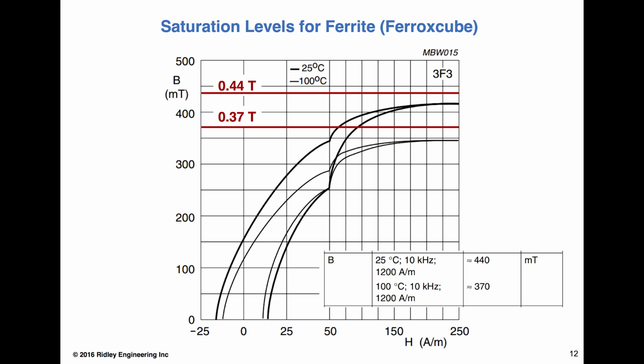We have to define what planar means carefully. Do you mean a PC board with a core over it? Or is a slab of copper running through either side of a window a planar? They all get called planars. But certainly the latter is applied in the megawatt area. Planar is never truly planar. It just means it's a lower profile than a previous design. But planar is certainly not restricted to PC board designs, which can have a lot of problems.